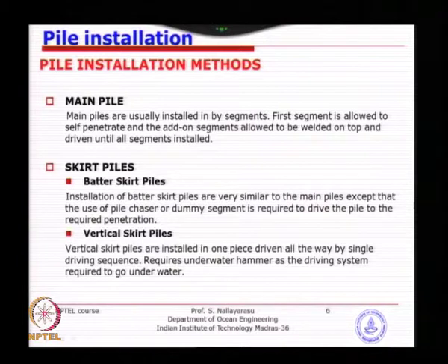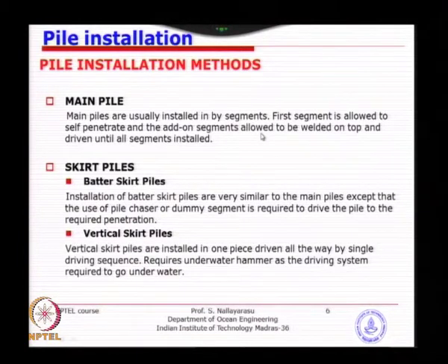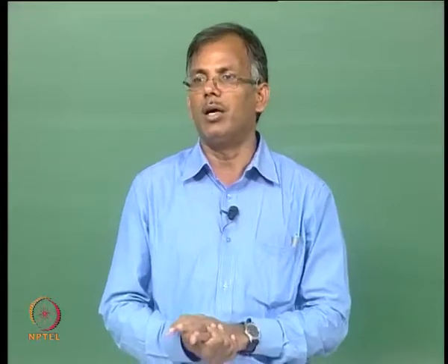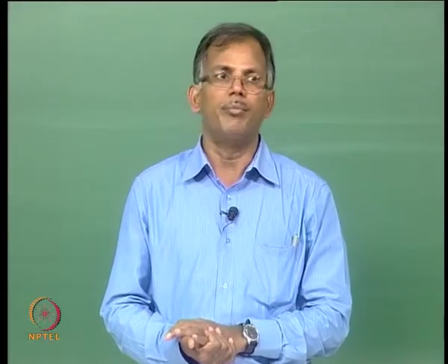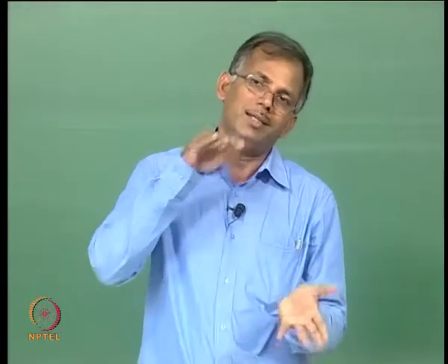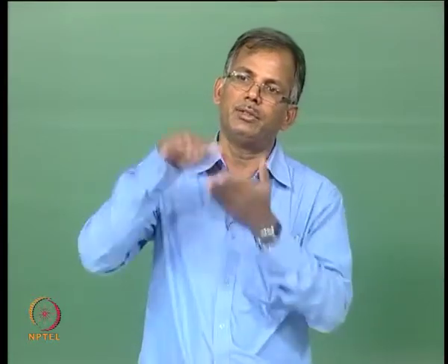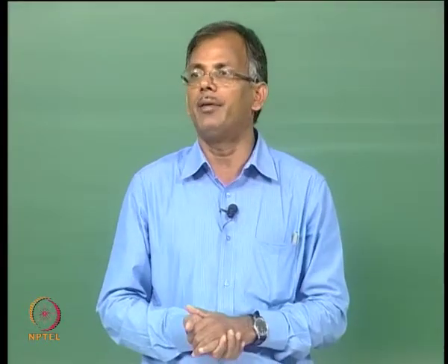So, main pile, skirt pile, I think we have introduced earlier in the design course, but in any case the main pile is installed through the main leg of the jacket by segmented construction. The first leg length will be slightly longer, as I mentioned, and it should have been calculated based on the length of the jacket plus self penetration plus the amount of sticking up required for us to drive.